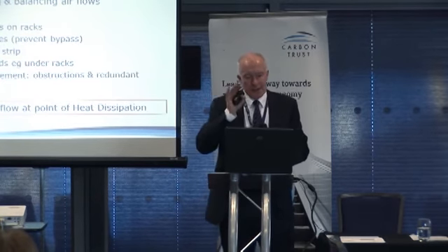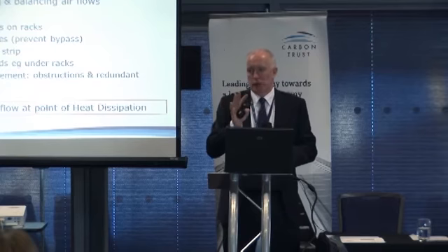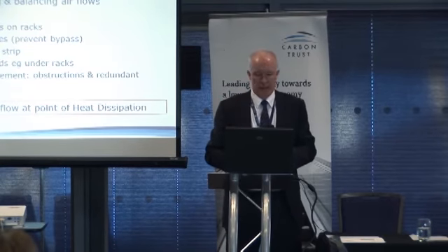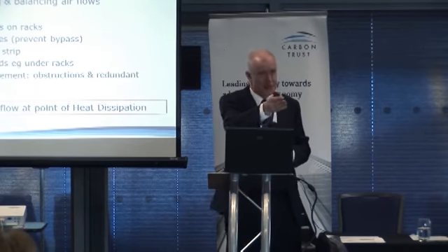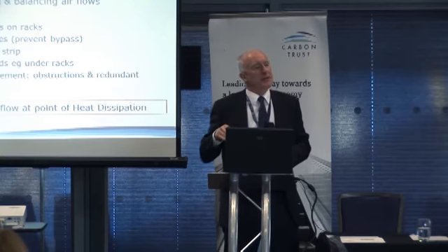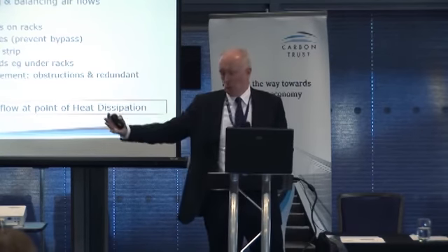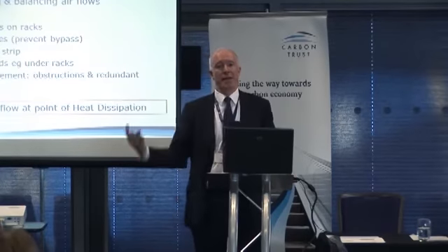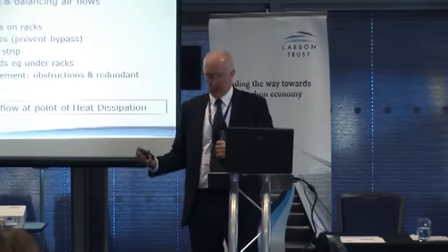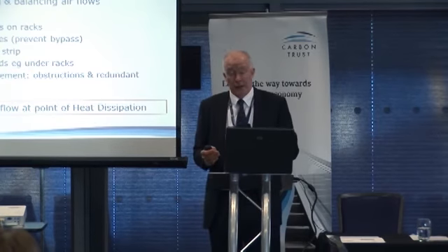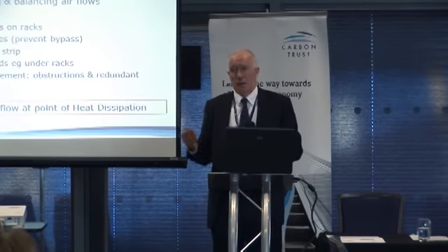I think it's important to get that understanding of the hot and cold air to people that are managing the computer suite. They may not necessarily have that at the moment. Balancing of the airflows came up. Where are the airflows going? Because they didn't have that understanding, you may have had a situation where you've got a floor distribution and you've got your diffusers that you can pull up and down and put the air coming into your room in different places. People have probably gone into the room and said, gosh, it's hot over here, standing at the back of a computer rack.